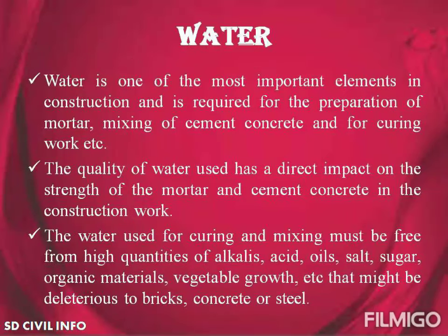The next construction material we are going to see is water. Water is one of the most important elements in the construction process, and it is required for the preparation of mortar, mixing of cement concrete, and for curing works, etc. Water plays a vital role because the quality of water used has a direct impact on the strength of the mortar as well as cement concrete in the construction work.